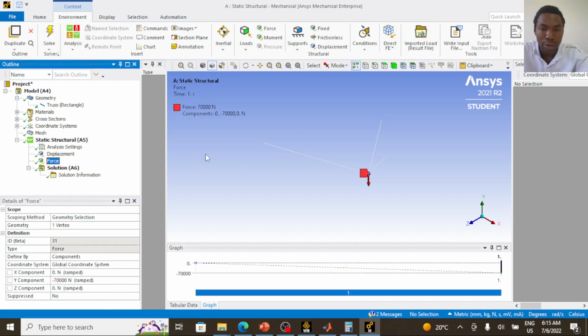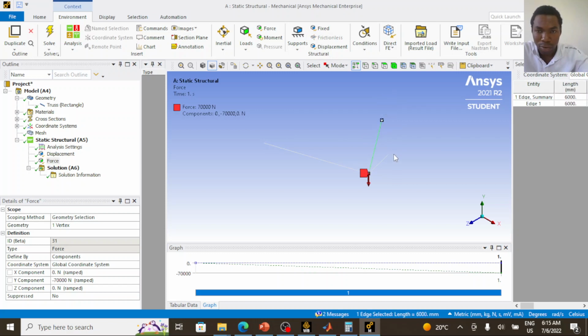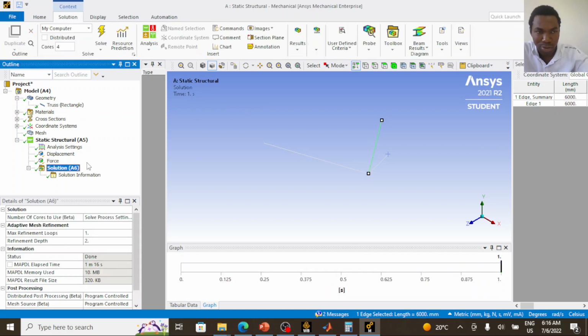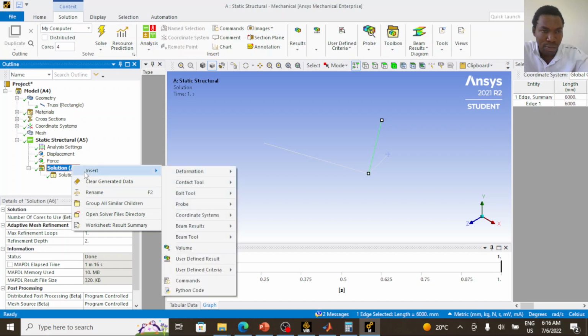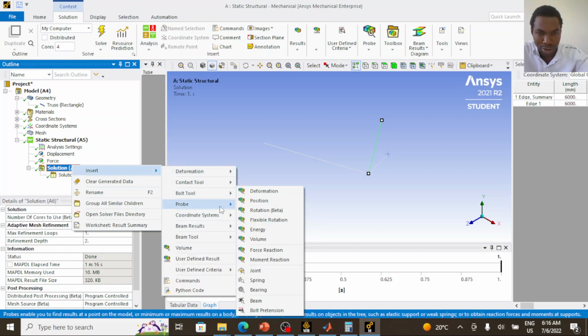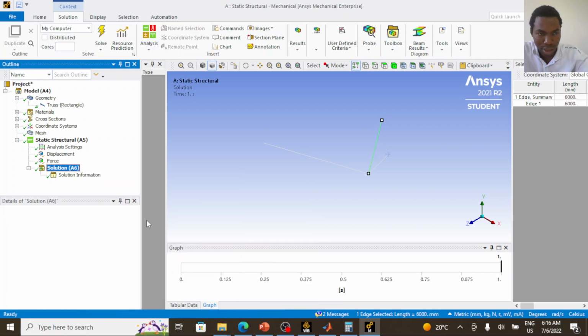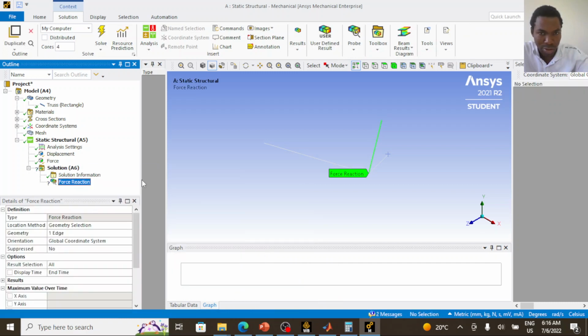So ANSYS has completed analysis now. Wow, it actually analyzed using one displacement support. I applied one displacement support at each of the nodes, and we know that at that node, our x, y, and z component displacement is 0. I'm curious how ANSYS will display the reaction results for me. So under the solution, I'm going to probe the reaction to check results.